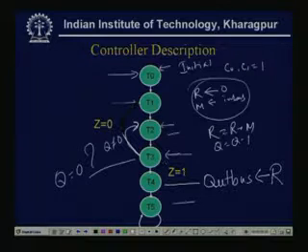If the present control state is T3 and Z equal to 1, then only in the next clock pulse it will be in T4. And if the present control state is T3 and the condition Z equal to 0, then the next state is T2 instead of T4. So, these are my control signals, that means present state and the input. Here the input is the signal generated after the condition, and then the machine will change.